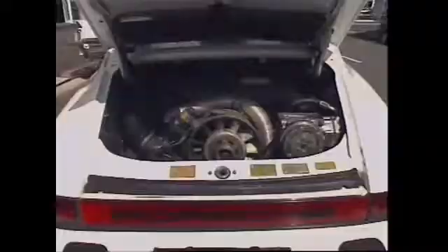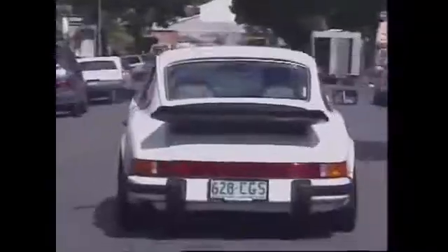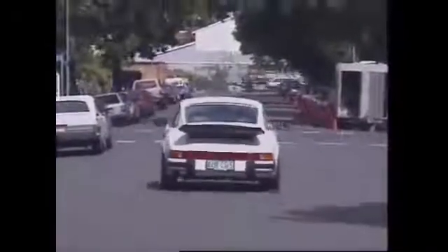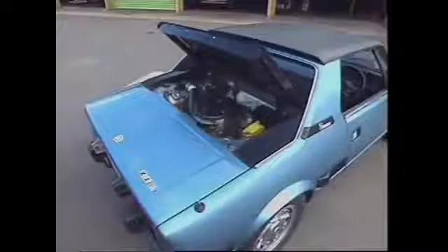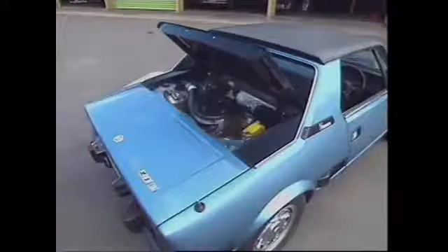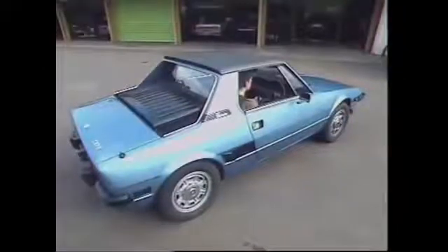Moving the engine to the rear allows a lower bonnet line, which improves aerodynamics. The increase in weight over the rear wheels can improve their traction. This vehicle has the engine located behind the operator's cabin, but forward of the rear driving axle. This is called a mid-engine rear-wheel drive vehicle.